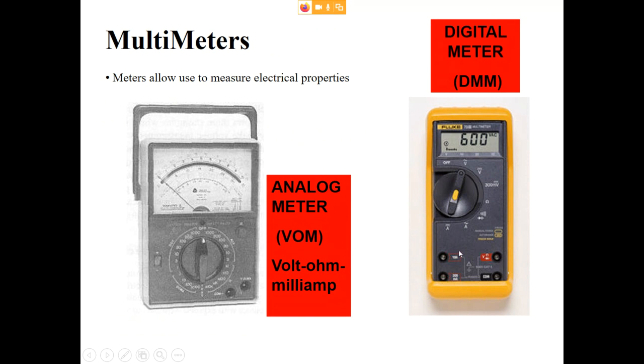You notice there's multiple terminals here. On the DMM over here, there's a red one that has a V and an omega. That's for measuring either voltage or resistance. Over here, there are little red boxes and it says A. That's for measuring current. So if you're going to measure current with a multimeter, you have to physically wire the meter into different terminals.